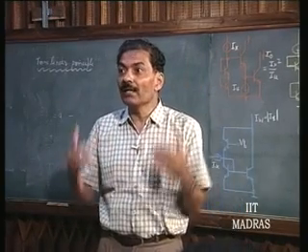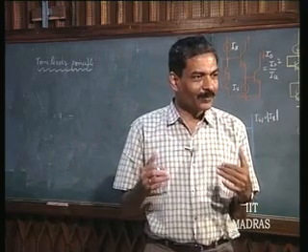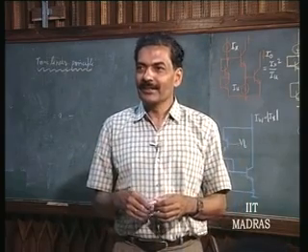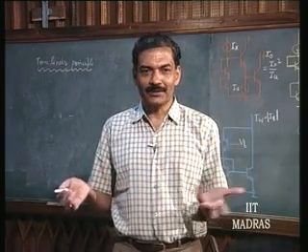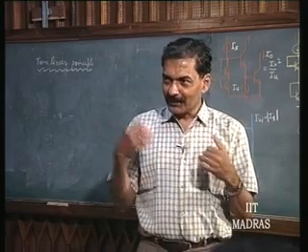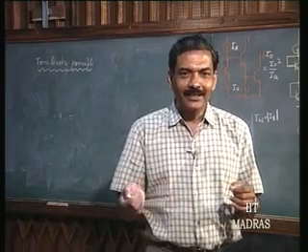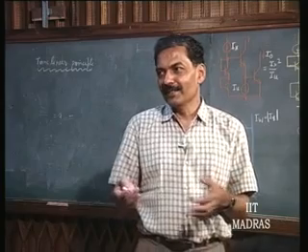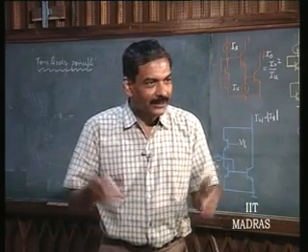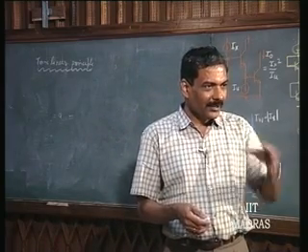Why is this requirement of equal number of diodes? Why should there be that requirement? If it is not equal, what happens? Kirchhoff's law will still be satisfied, there is no doubt about it. Just can you think of, in our expression for these things, we had IE naught coming at the denominator. Those will not cancel, and the entire purpose of our signal processing gets lost. It becomes device dependent.